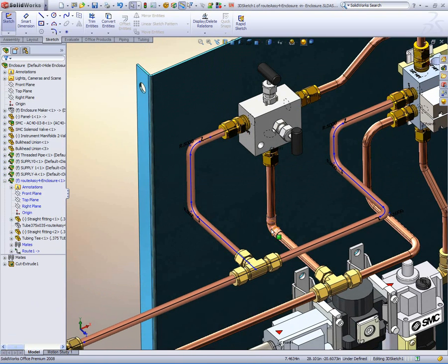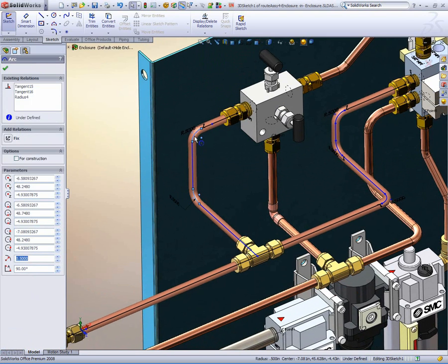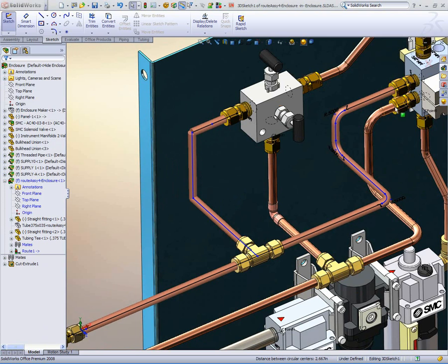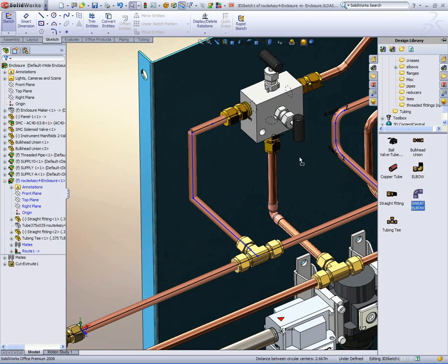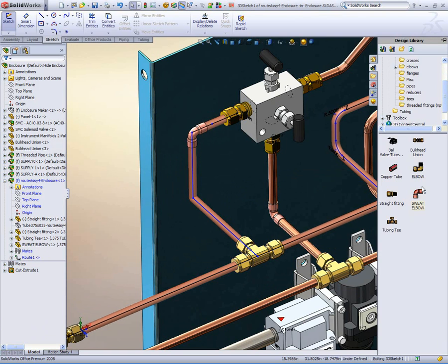Now just to change things up, you'll notice that there are some sweat fittings in the corners. SolidWorks is very flexible, allowing me to use bent pipes, or in this case, we'll just delete the bend information off and use a sweat fitting by dragging and dropping. Place 2 of those into our design.